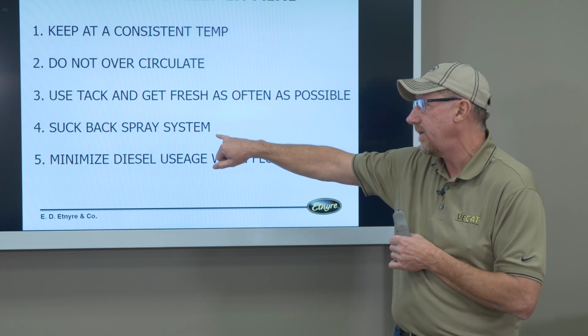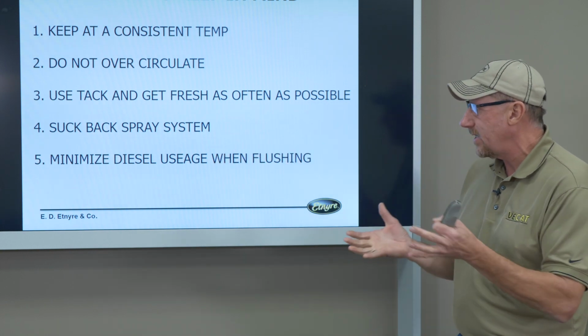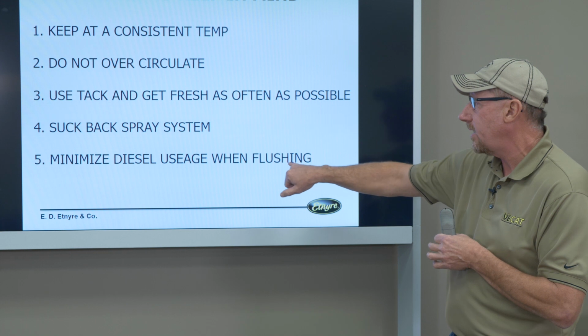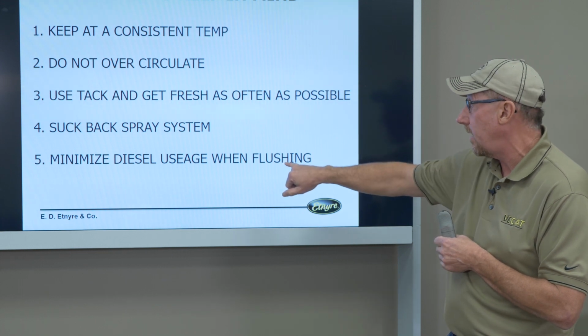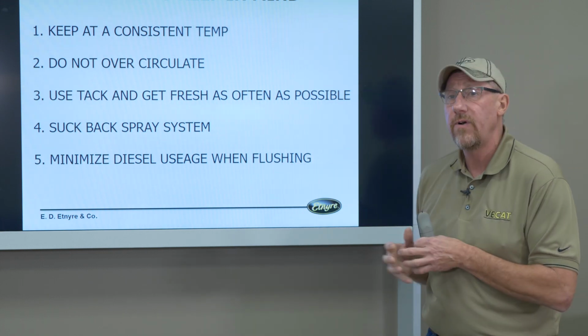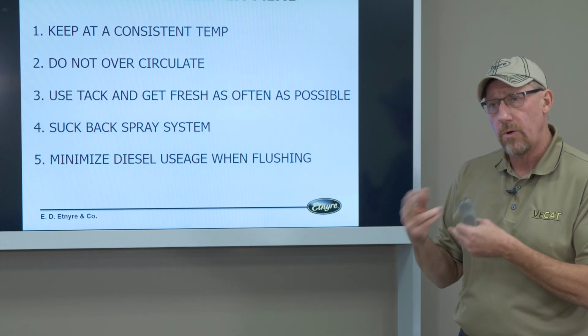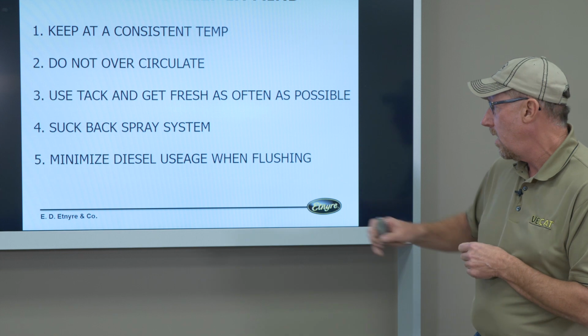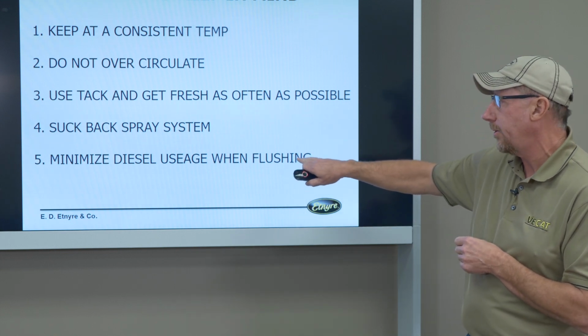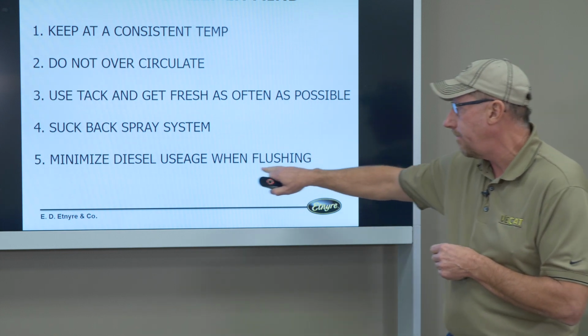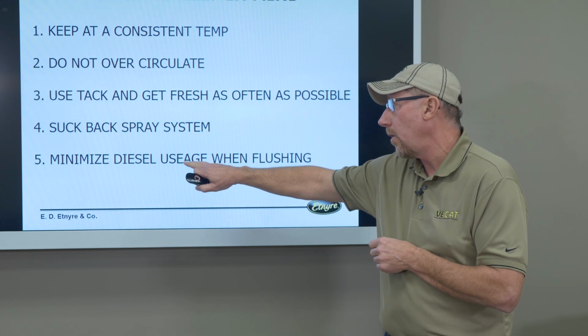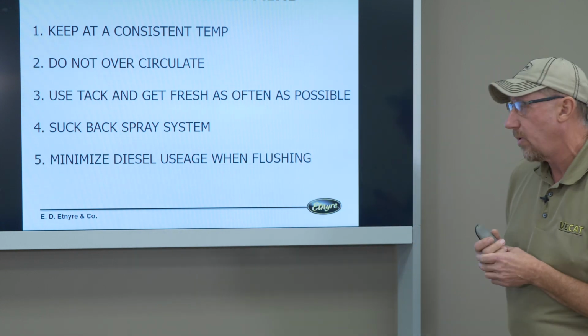Suck your system back at the end of the day. Make sure that everything's clean and back out. And because we're using a tack that's an emulsion, we don't have to use very much diesel fuel to clean out our system. Okay? Just a very minimal amount to rinse the pump out, and we're good to go. A lot of people, especially when it gets colder out this time of year, we want to make sure that we don't overuse the amount of diesel and ruin our product.